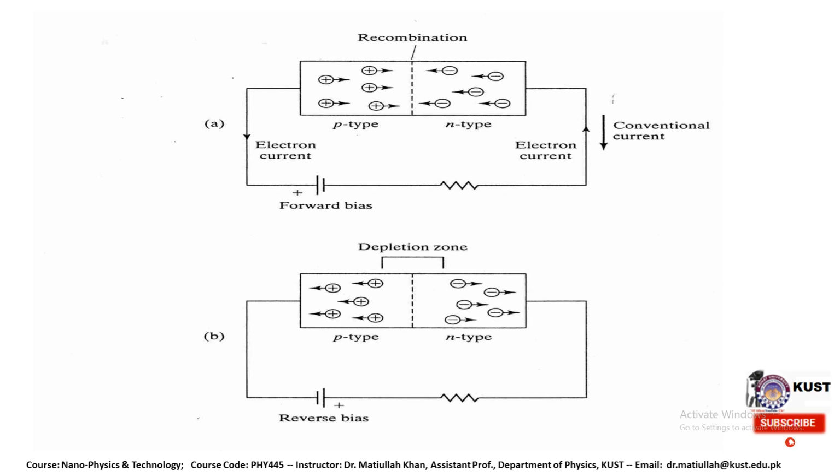So this is actually the reverse bias configuration of the p-n junction, where p-type material is connected with the negative terminal of the battery, and n-type is connected to the positive terminal of the battery. So that will not lead to the current, otherwise it will increase the width of the depletion region, and further, if we continuously increase the external potential difference, there might be breakdown that will rupture the barrier, and there will be no existence of the semiconductor diode any further. So this is the reverse breakdown that occurs in the reverse bias configuration of the system.